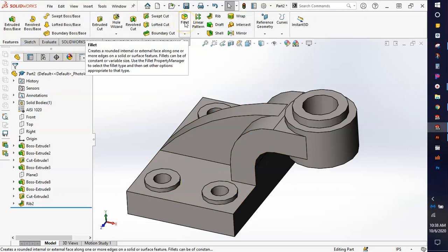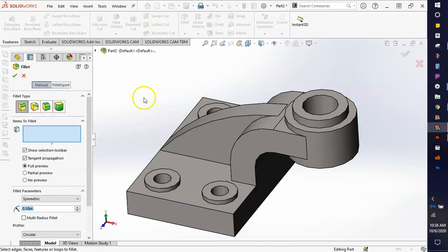There are a lot of fillets. So it says all fillets and rounds are 0.05. And then we just need to go through and fillet anything that we see that has that little curved stuff on it. So the bottom of it's probably going to be flat. Means we can't just click on these flat sides because it will also fillet the bottom. So you do have to do this line by line, which is rather tedious. So if you just follow with me here, I'm going to go line by line and do the entire thing.